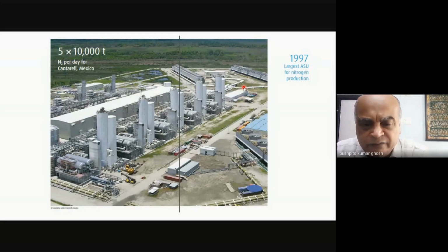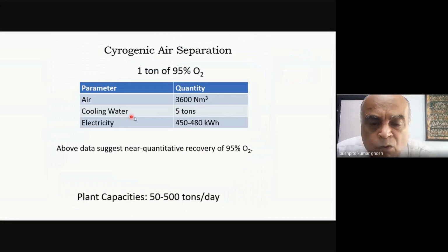process. And likewise, the engineering feat of Linde is what really enabled him to make the Joule-Thomson effect and liquefaction of air into something that he could utilize to separate out oxygen and nitrogen. If my objective is only to recover oxygen, then of course I can use the liquid nitrogen to greatly reduce the power consumption for compression, because a lot of the cooling is going to be done by the waste liquefied nitrogen and the cold nitrogen streams.